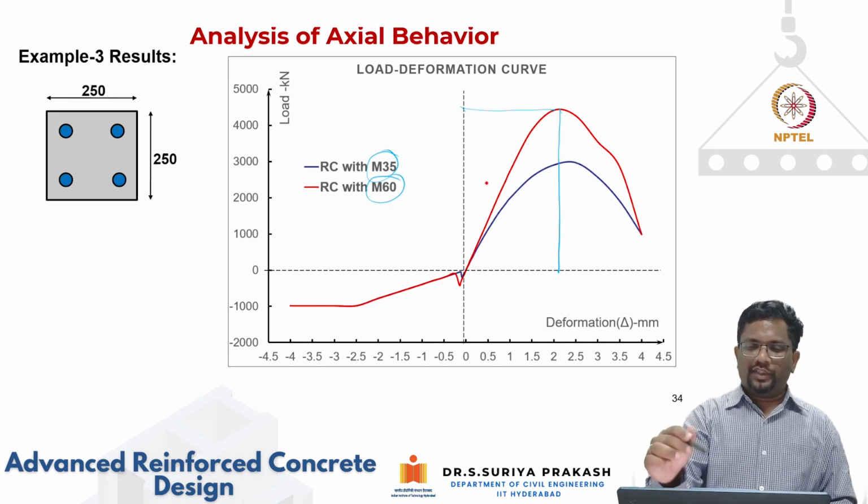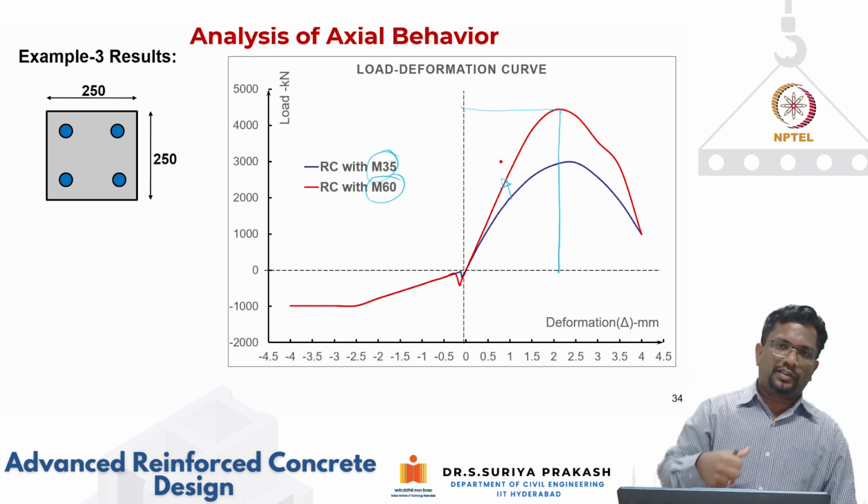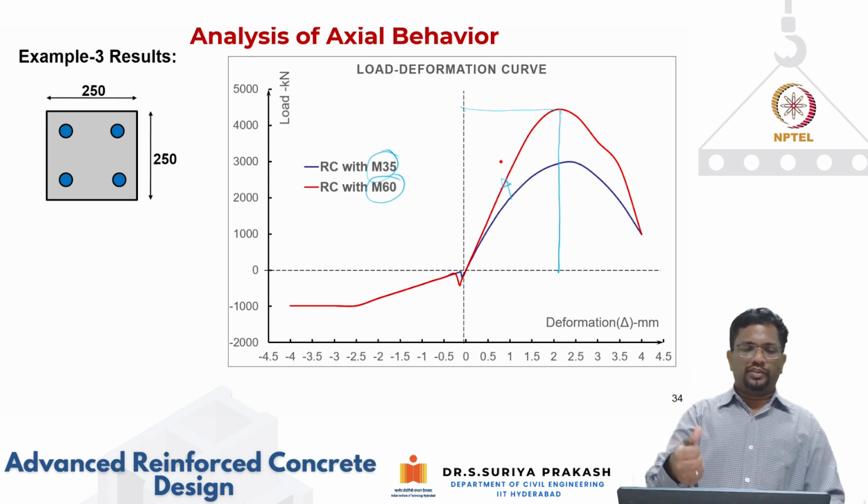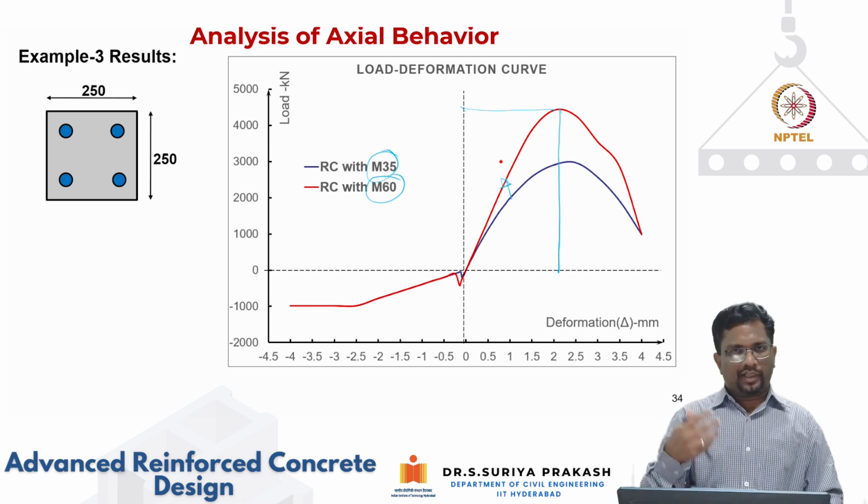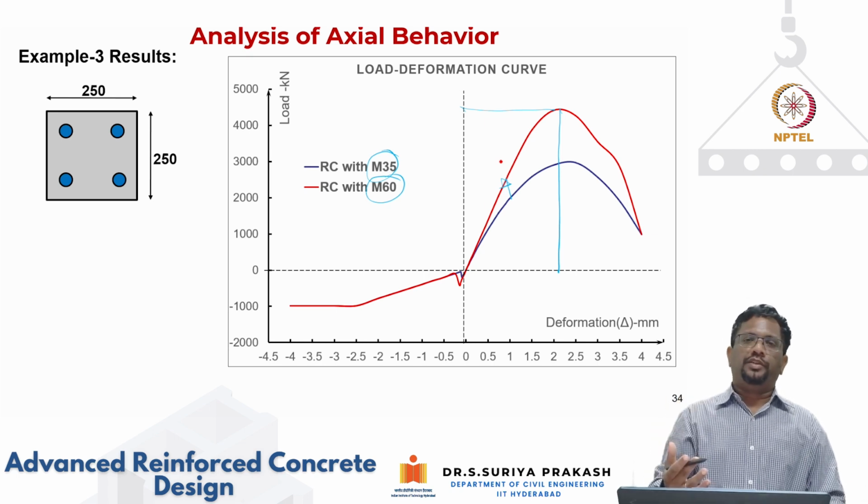Another thing is, with the increase in strength of concrete in compression, of course my elastic modulus, or the stiffness of the member, has increased as expected, because concrete is a major load contributing component in an RC member for compression.